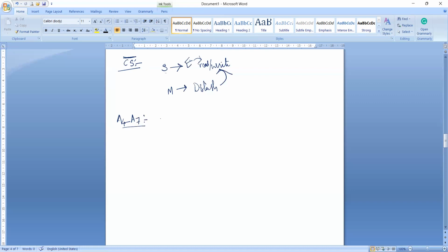Next, the A4 to A7 lines. These four lines are the higher nibble of the lower byte address generated by the DMA in master mode. The 16-bit address A0 to A15 will be there; A0 to A3 we already discussed. In slave mode, these act as inputs which select one of the registers to read and write the data.